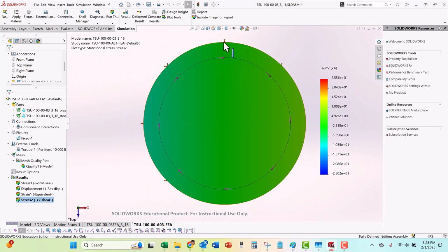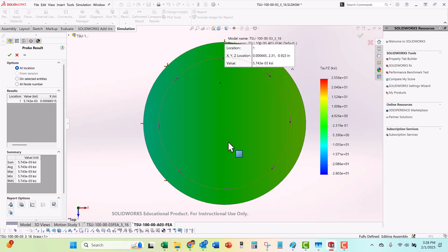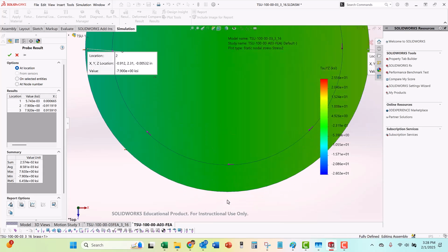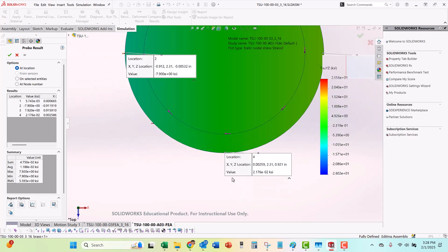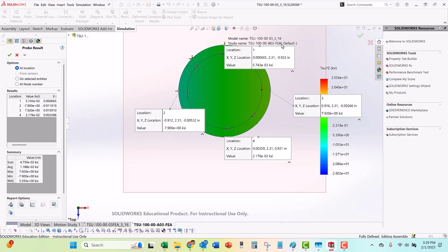And so if I probe here and here, well, I want to probe all four of them, then we'll talk about it. You go to Plot Tools and say Probe, and you want to probe it right at the perimeter, right at the very perimeter, on these quadrant points. So I got those two, and then it looks like in the middle, get as close as you can to the edge, right in the middle. So let's look at these values.